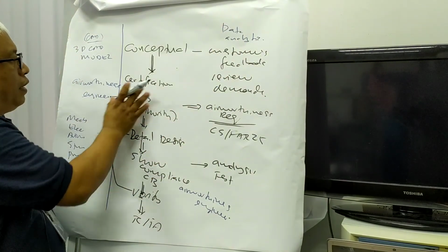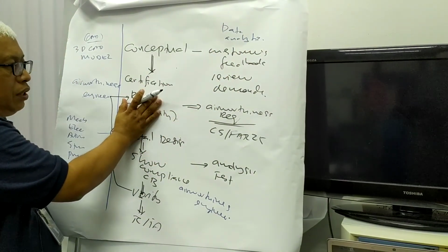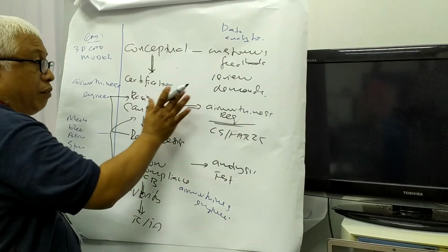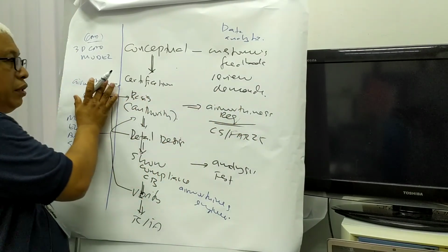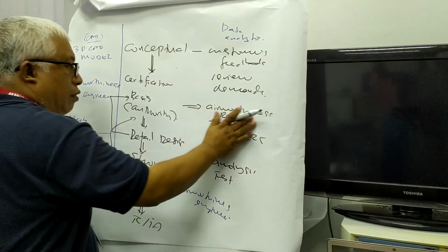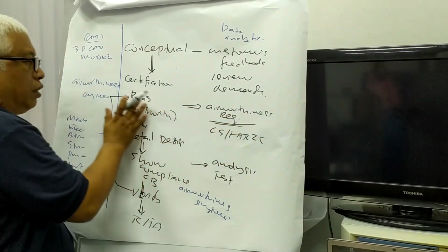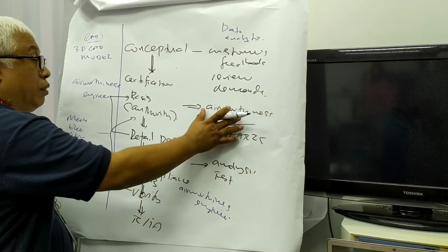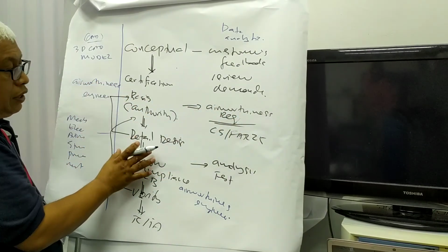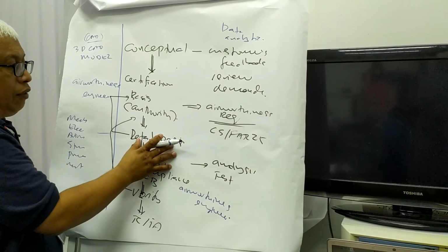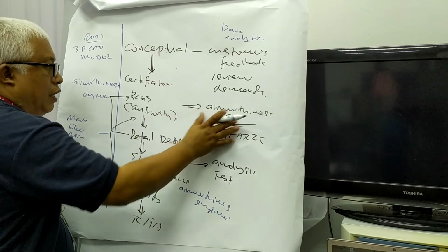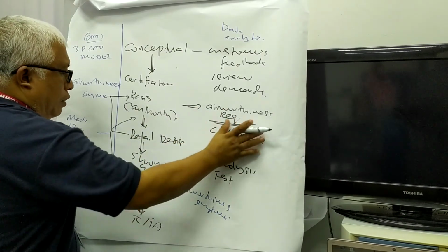Then we go into the airworthiness requirement. We develop the cert basis, primarily the airworthiness requirement, and we have engineers who interpret this airworthiness requirement line by line to ensure we can comply with this. And that information comes to the detail design, where the detail design will do the design detail plus show compliance to every line of this airworthiness requirement.